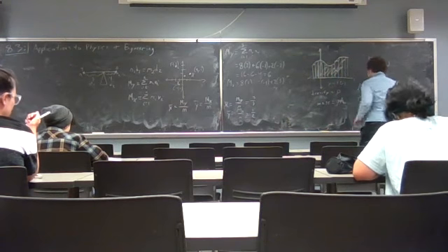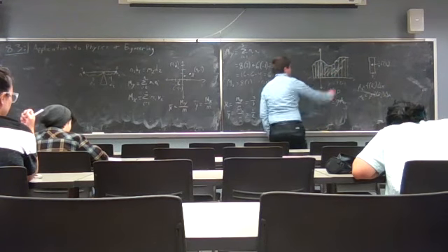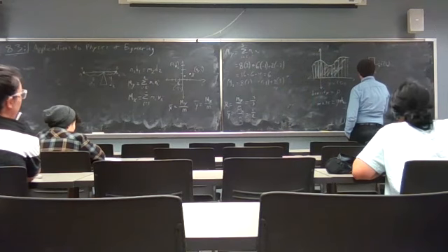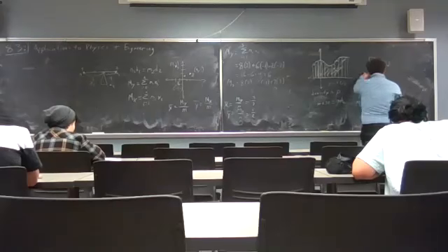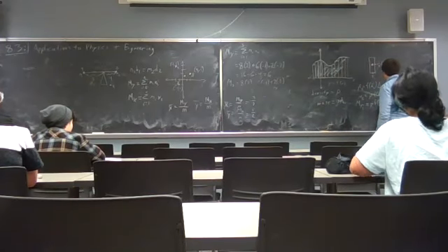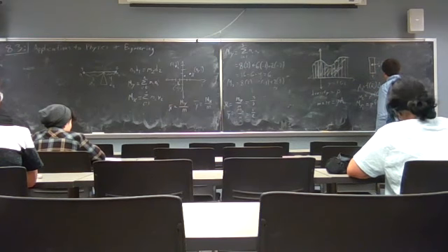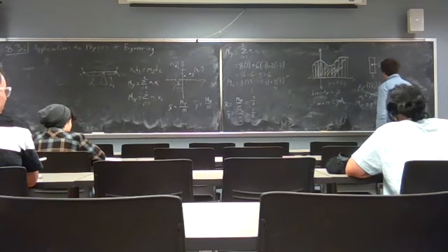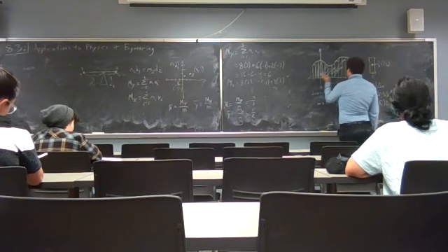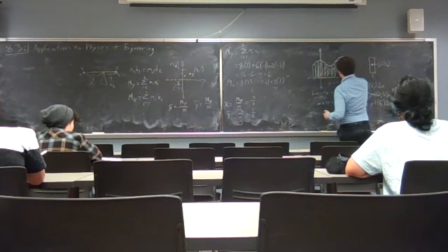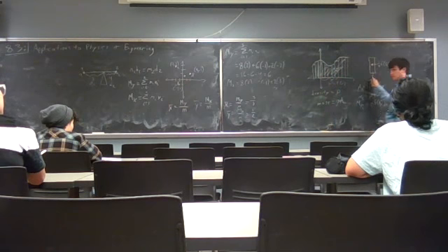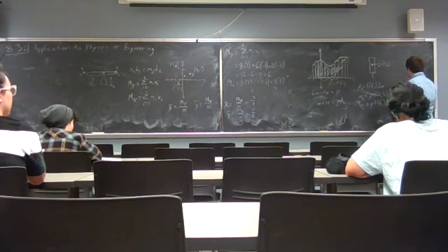So the moment, I'll write for M_yi, basically for my rectangle. I'm going to take rho times f of xi bar times delta x times the distance from my origin point to that rectangle, right? So let's say it's this rectangle. Well, that would just be the same xi bar. So I take this and multiply it by xi bar.